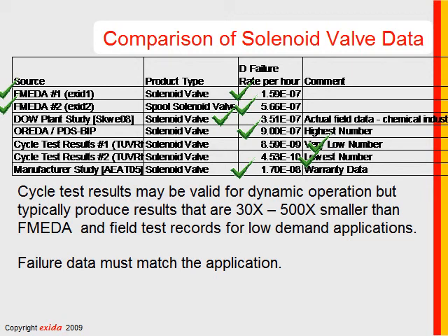I've seen one or two, but for the most part, cycling isn't done until there's a demand or a proof test. So you might find a product sitting around for years. These low failure rates would lead people to conclude they don't need to do proof testing. It would lead people to conclude they don't need redundancy. In other words, it's dangerous. Safety is serious business.